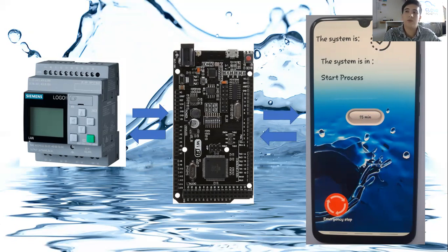So I had to find a way to extend my output range, which I will explain later on. And then on the board itself, there's a Mega and an ESP8266, and they communicate through serial. And then the app communicates with the Arduino board with a Wi-Fi UDP connection, which I will explain later as well.